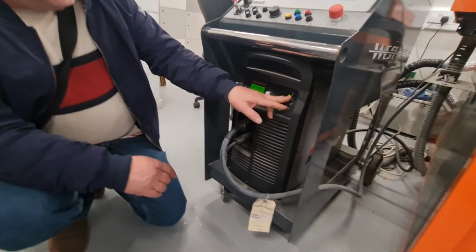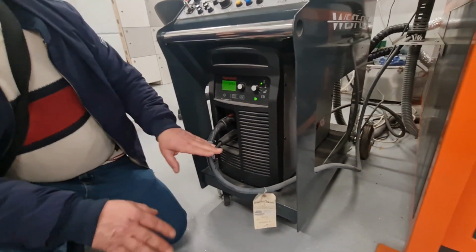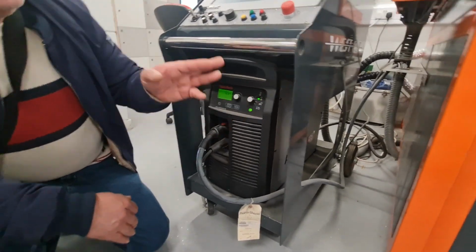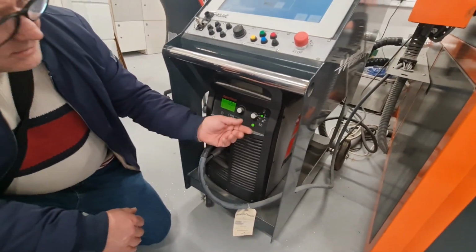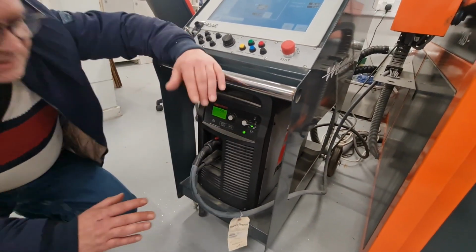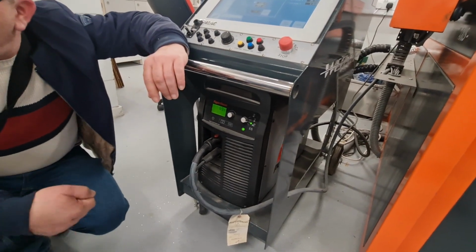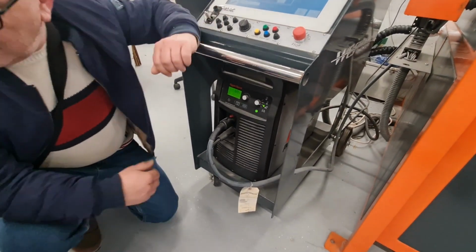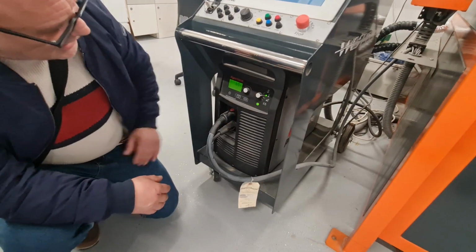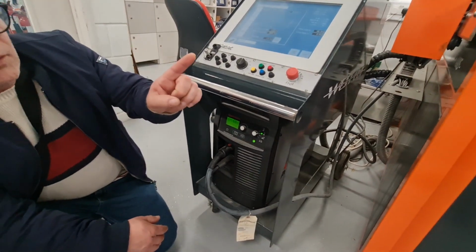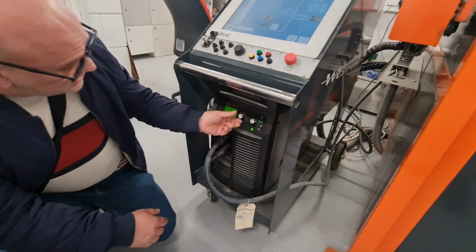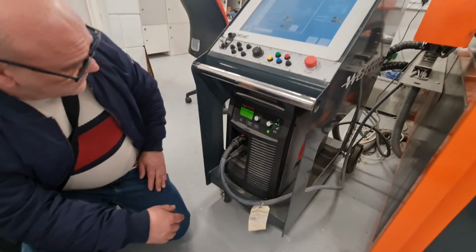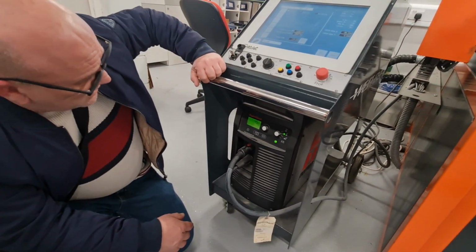You have an expanded metal, so the machine can keep continuously cutting. This one is the normal way to work. This other one, in this case, you don't use it because this is gouging. For example, you need to weld and you need to make a bevel cut or clean a weld or something. So normally, you should be there. Now, we install the consumable, so it's 45 amp. So this has to be 45. Okay? Now we should test.